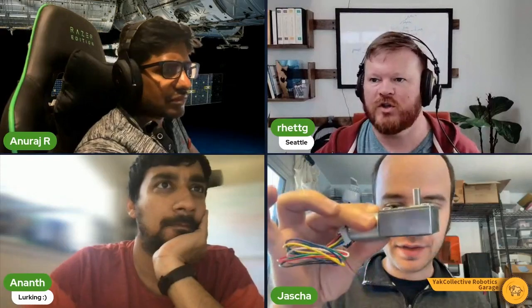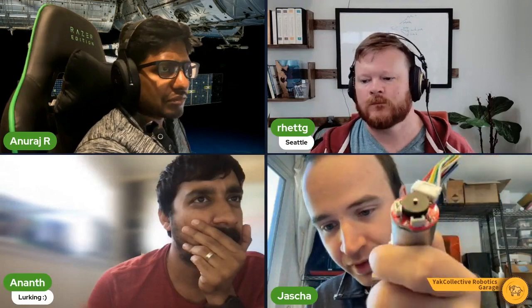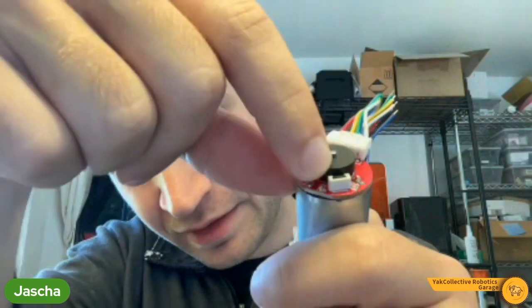Yeah. JGY worm motors. They come in all kinds of different gear ratios, which is nice. And they're pretty common. The ones that I got in particular have a feature which isn't everywhere. So, standard gearbox and then brushed DC motor. But what it has is an encoder on the back. So this is really a nice feature. This is actually a magnetized ring. And here, if you want, I could grab my magnet viewer film real quick.